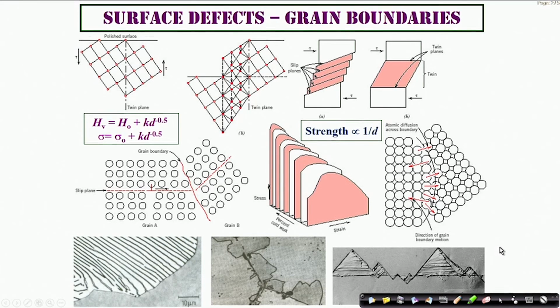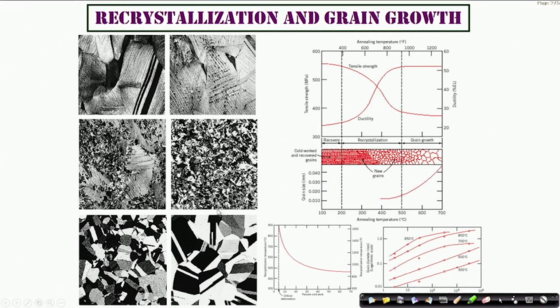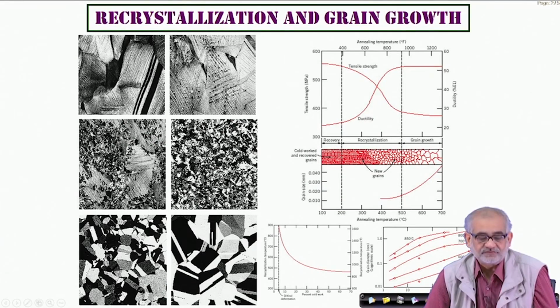But all these various shapes, or the very presence and identity of various kinds of two-dimensional defects, have a very great influence on the overall properties of the material. And this is just an example to show you how different kinds of boundaries can arise. If you deform a material and then anneal it so that it recrystallizes, you form very tiny little boundaries. So the microstructure can be varied to a large extent like this if you apply different kinds of thermomechanical processing.